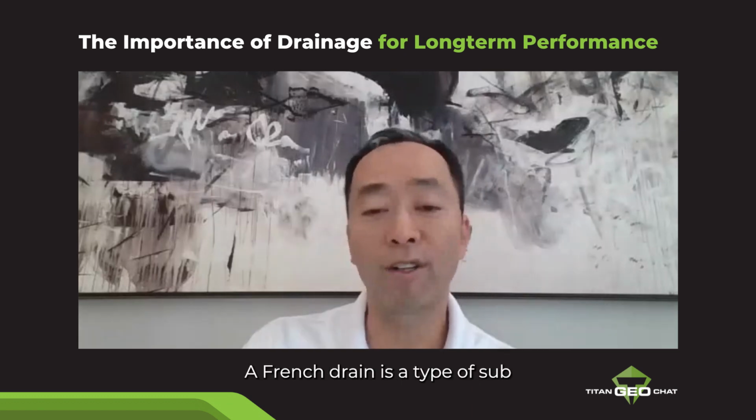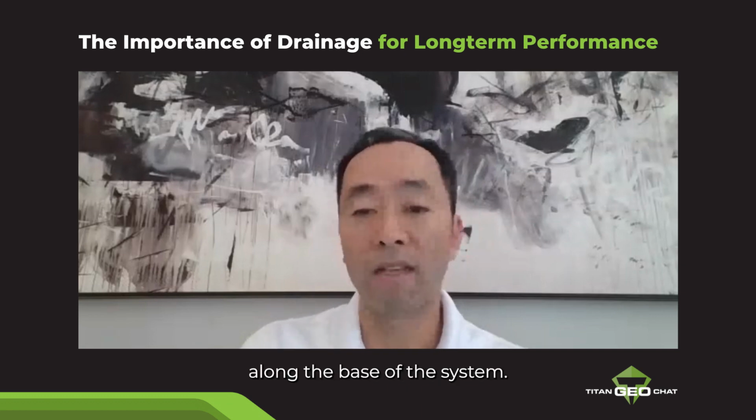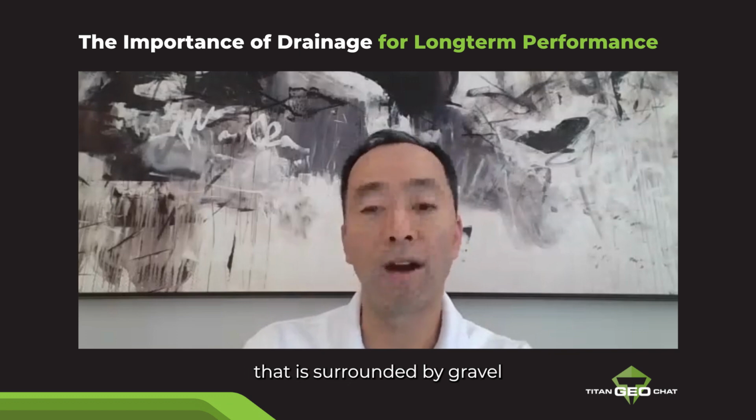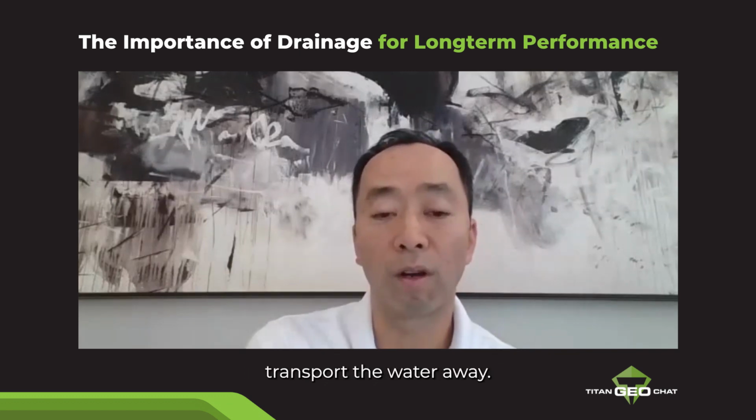There's also French drains. A French drain is a type of subdrain system that can be installed along the base of the system. It consists of a perforated pipe that is surrounded by gravel and other porous materials, designed to collect and transport the water away.